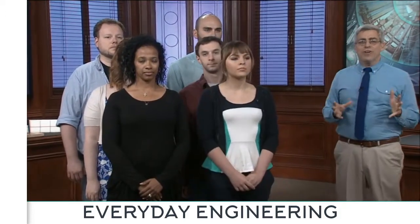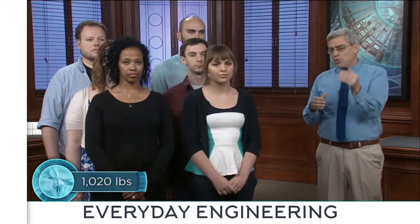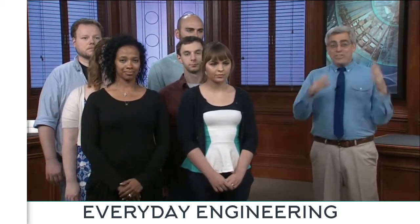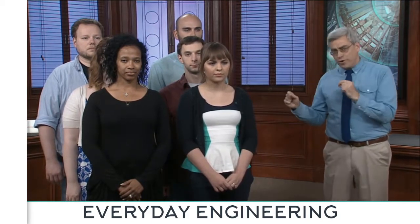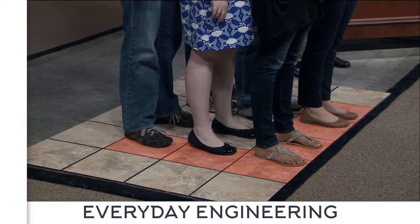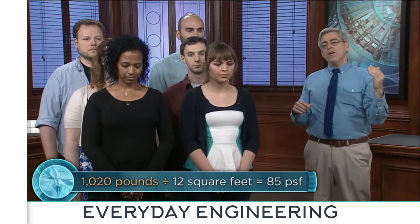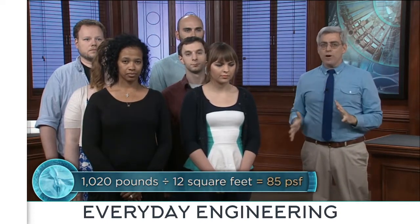Now, prior to this lecture, I asked each of our volunteers how much they weigh. And the total of all 6 weights works out to 1,020 pounds. Yes, this is half a ton of people. As you can see, our volunteers are occupying approximately 12 of the squares on my floor grid, 4 along the front, 3 along the side. And so the live load represented by this very tight grouping of people is 1,020 pounds divided by 12 square feet equals 85 pounds per square foot.